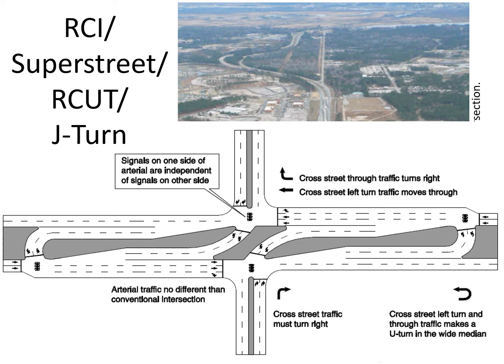Here's an example of a signalized RCI. We have signals at the main intersection, two signals, and signals also at the U-turn. These don't have to be signalized, and I'll show a couple of variations of this. It can be useful in certain circumstances. The nice thing about an RCI is you can get perfect progression because essentially each direction acts like a one-way street. So from a signalizing perspective, you can get a lot of efficiency and benefits there.